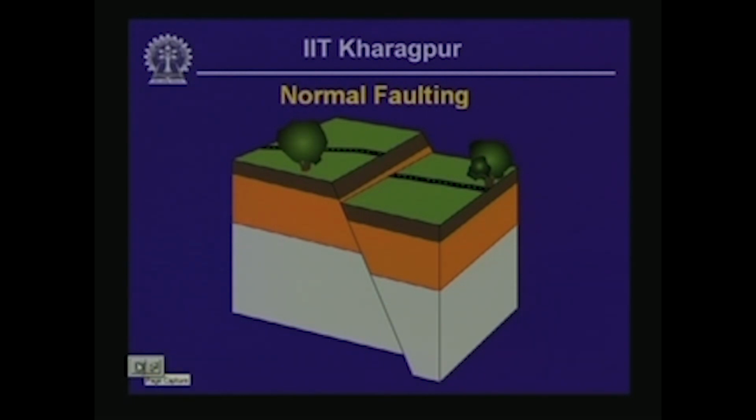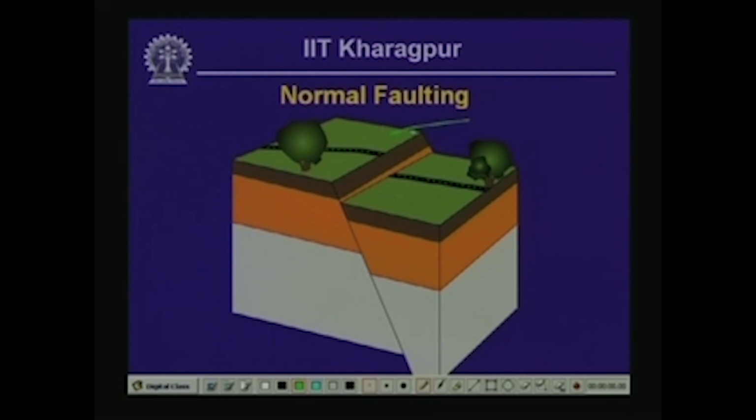This is the ground surface. You might have understood that already. Different layers of rocks and soils are shown using different colors. This one essentially is unit 1, the surface layer. Then you have unit 2, that could be another soil layer, and this one here is unit 3, which could be a rock layer. Now, we have to describe the geometry of normal faulting.